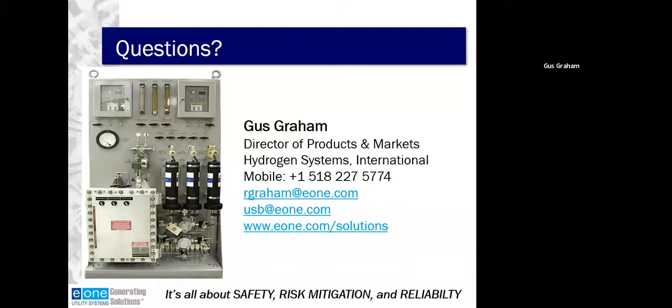Okay, good question. That varies based on the gas that's being calibrated. So it's probably best, I don't want to repeat incorrectly the information that's going to be provided by our great lead service technician. Chad will be reviewing that during the video, and he'll walk through what the standard ranges are expected on each of those voltages as you apply those gases. During normal operation, the sample voltage should be between 3.5 and 4.0.